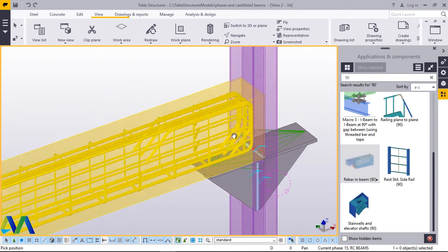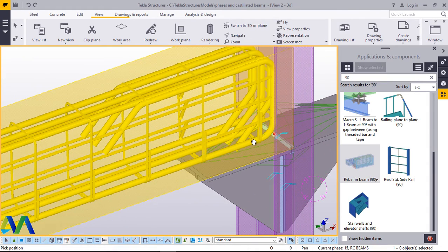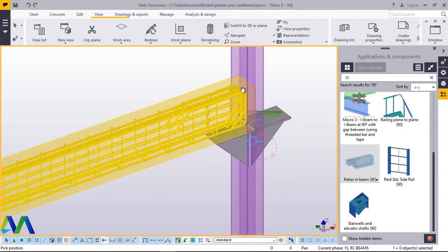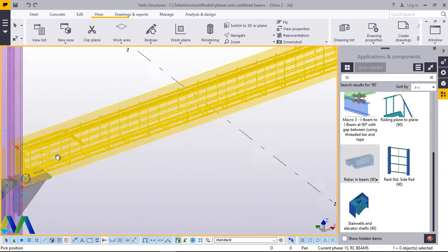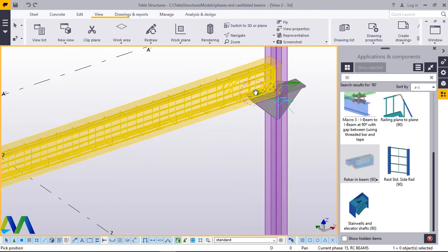You can see that. And remember, I told you that to enhance the support of this beam, after doing all your bending, please, on the bottom end of the rebars, ensure that they're welded against the stab plate, and the top bars are welded against the column, same to this end, prior to doing your formwork and casting the RC beam.